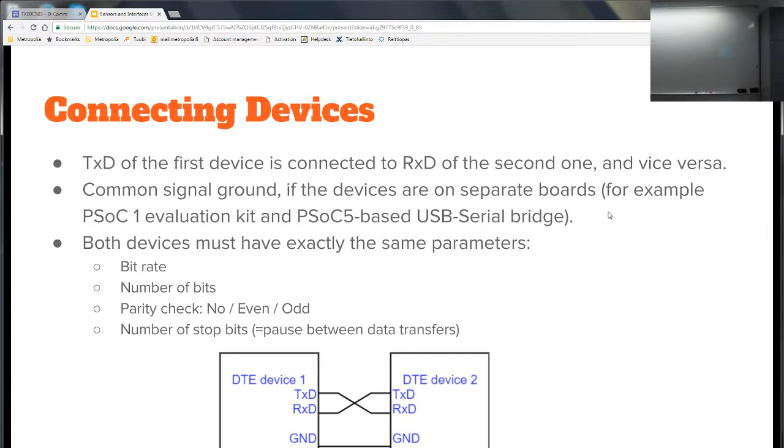Okay, most commonly there is no parity check nowadays anymore. Lines are short, not anymore, say 300 meters or so. So the old RS-232 standard supports 300 meters per cable, and that was kind of the state of the art at one point, before someone noticed that the consistency on the quality of these telephone lines is good enough that you can actually use balanced data transmission.